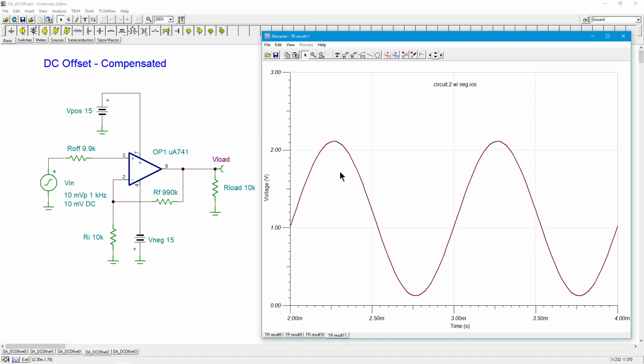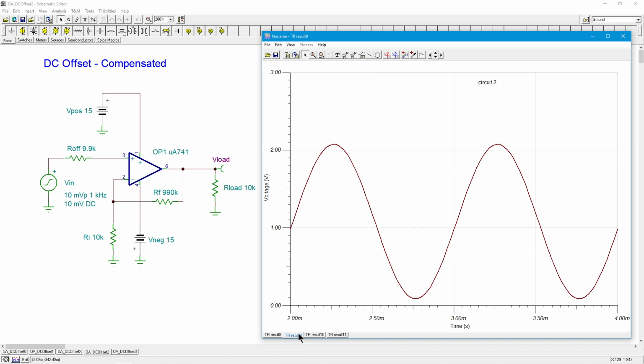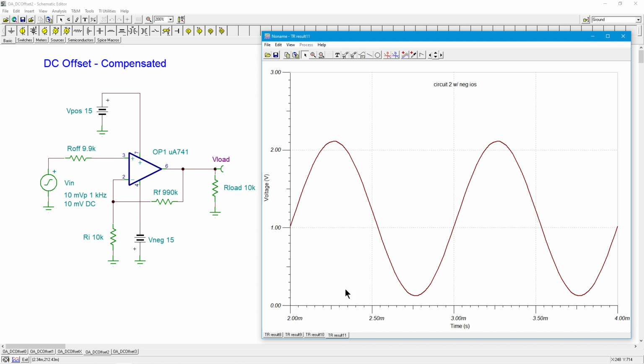So, hey, look, it's worse, right? Because back here, those two things were partially canceling. Over here, they're going off in the same direction, so that's worse. And I can look and say, yeah, look, dropping the resistor down is actually better than that case. So sometimes it'll actually work out that the bigger resistor will give you a lower offset.